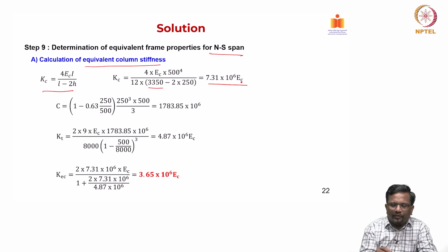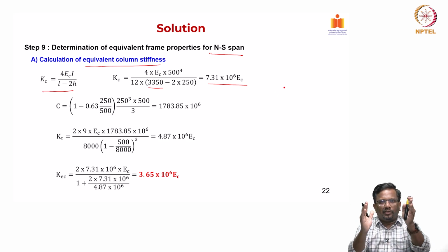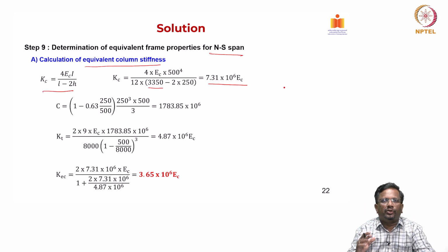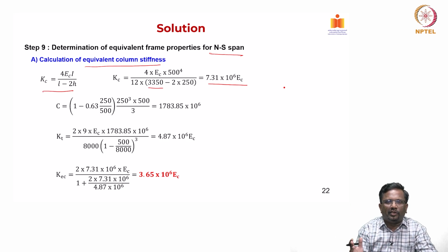Now, torsional stiffness. For that particular width of the column, you take the thickness of the slab and assume that there is a beam acting in the transverse direction. Though this is a flat slab and there is no beam, a part of the slab in the transverse direction will contribute in torsion. That is what we are trying to calculate the stiffness for.